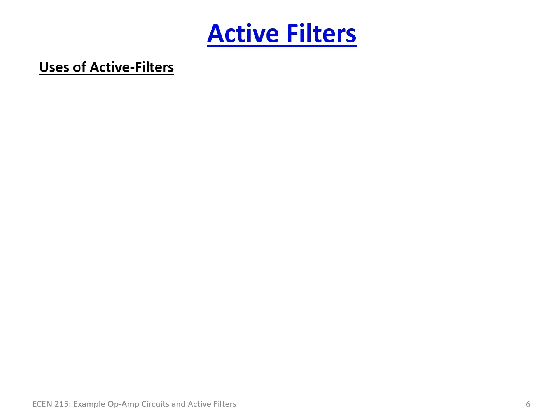So these are the actual reasons why you would use an active filter, specifically in the case of where you would be using this in your discipline in the future. First of all, you would have a case where you have some sort of sensor signal and it's got noise for whatever reason. There's lots of noise generated by power lines. There's noise generated by fluorescent lighting, or there are high frequency noise sources caused by motor controllers, because a lot of the time we're using pulse width modulation at a very high frequency, usually in the tens and hundreds of kilohertz.